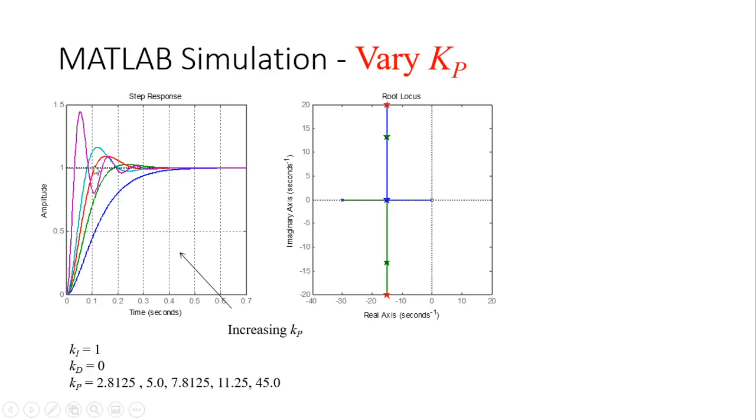So what I did was look at the root locus, because for me that's the best way to look at how the transient response changes. When you vary the Kp, it looks like this. This is, I think, when you have a double root, the repeated root. Then it moves along the vertical line when your system is underdamped.